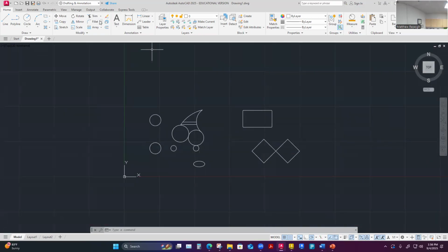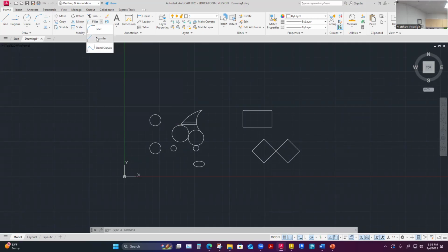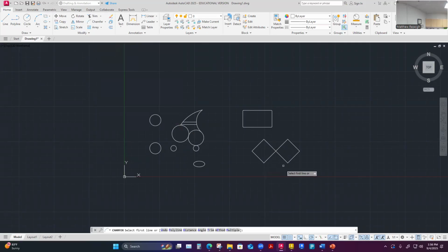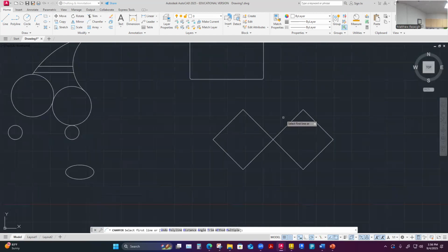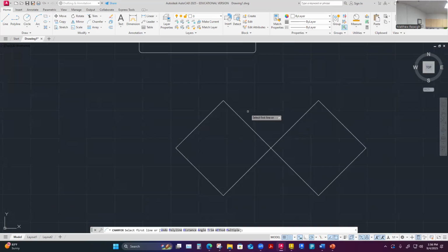Okay, fillets. The opposite of that would be chamfers. Not opposite, but a like function of that would be chamfers, only not with a round edge, but a beveled edge is kind of how we would look at this. So chamfer also can be used for a lot of different purposes in mechanical applications. A bevel is one, but there's reasons why I would chamfer corners down.